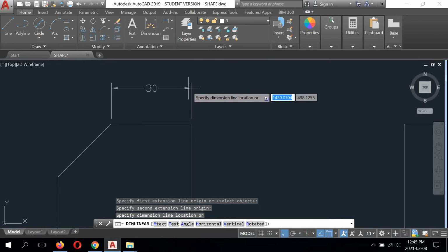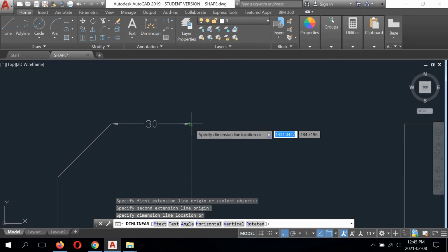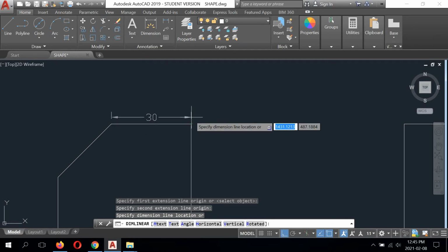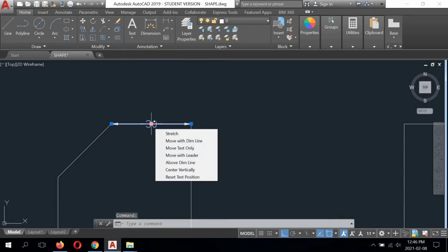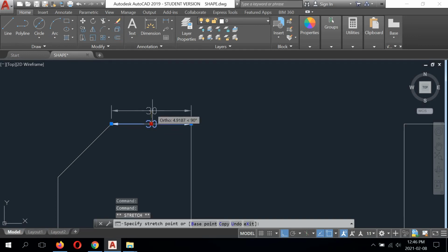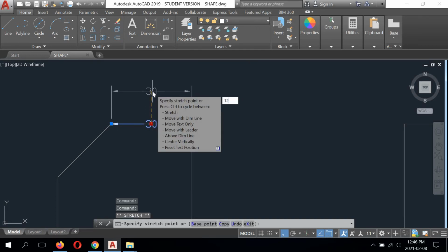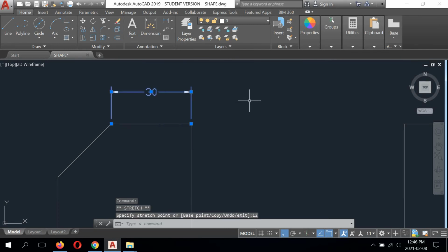Now, the best way to ensure that you get your 12 millimeters is I would snap the dimension right in line with the part like this first. This doesn't have to be done every time, but I'm going to show you why this makes sense. So once I've run that one, snapped it right in line with the part, I'm going to grab it at the value and use a grip. So left click the node, pull up, and type in 12. And that is going to move it 12 millimeters.